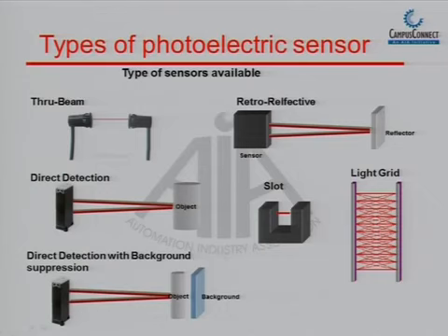If you talk about the packaging industry, the material that is supposed to be used is stainless steel. You cannot use mild steel as the material for conveyors. Now, if you have a biscuit packet moving on a shiny conveyor, there is a possibility that the light will get reflected back and give you false sensing. For that purpose, there are sensors called background suppression sensors. That means if this is the height of the target, it will suppress anything below that. It will only sense the target and not the background. Even if there is a shiny surface, it will not sense it.